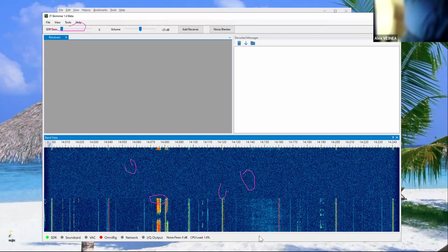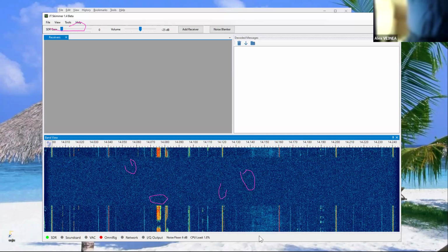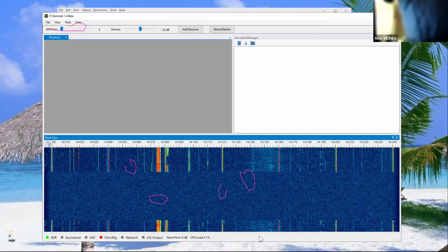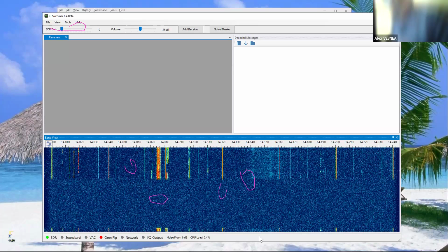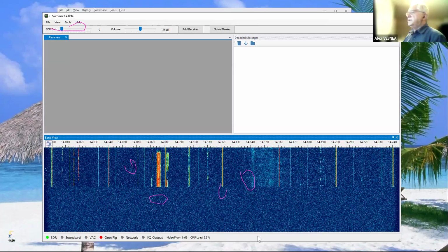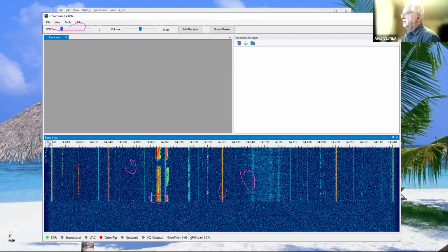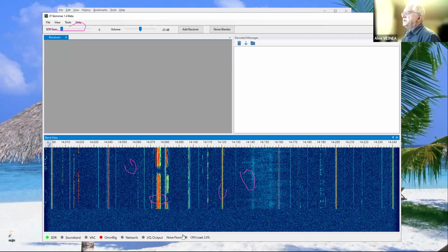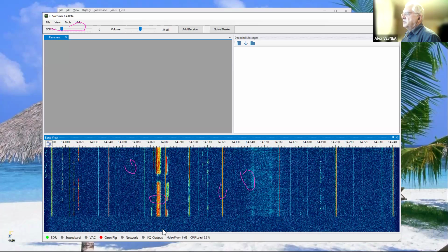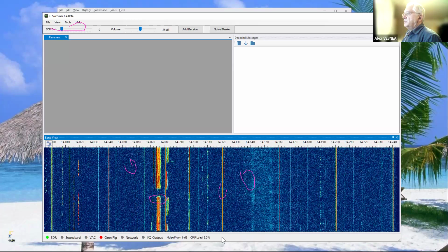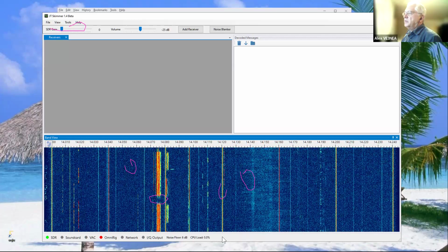And when I connect the antenna, I know how much atmospheric noise I have. It's about 6 dB. So as you know, this is the optimal value. If you have more than 6 dB, these extra decibels you still don't use for your dynamic range. If it's less than 6 dB, then you can improve your sensitivity by adding more gain.